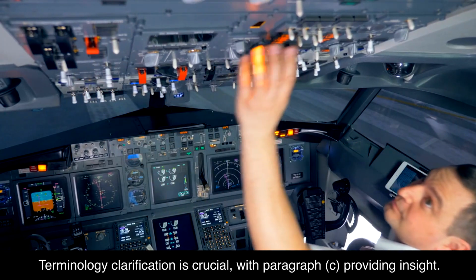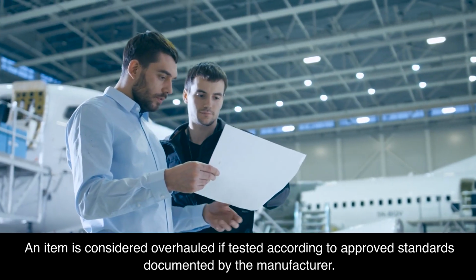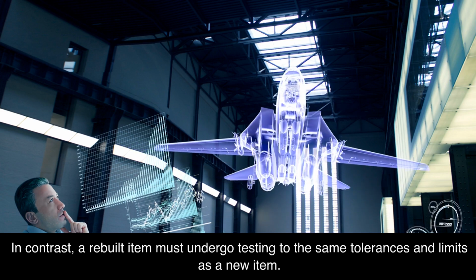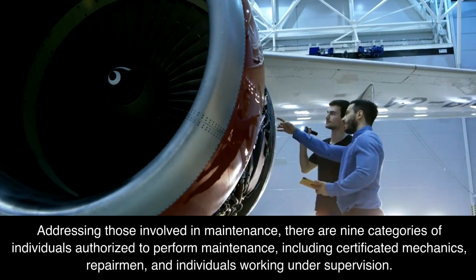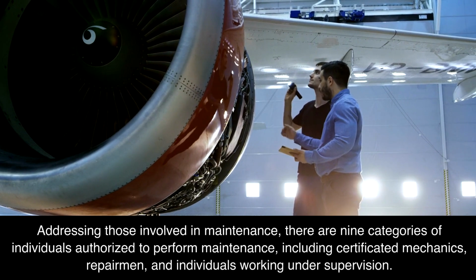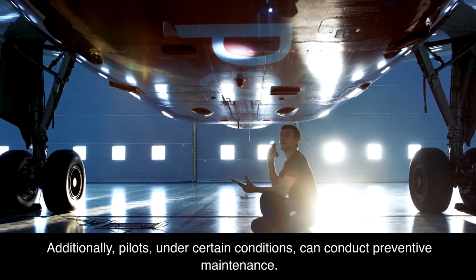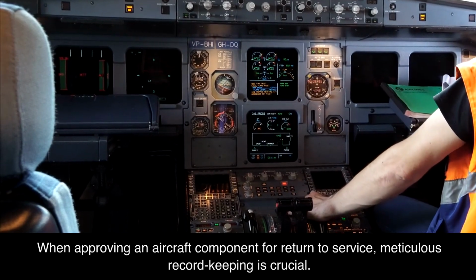Terminology clarification is crucial, with paragraph C providing insight. An item is considered overhauled if tested according to approved standards documented by the manufacturer. In contrast, a rebuilt item must undergo testing to the same tolerances and limits as a new item. Addressing those involved in maintenance, there are 9 categories of individuals authorized to perform maintenance, including certificated mechanics, repairmen, and individuals working under supervision. Additionally, pilots, under certain conditions, can conduct preventive maintenance. When approving an aircraft component for return to service, meticulous record-keeping is crucial.